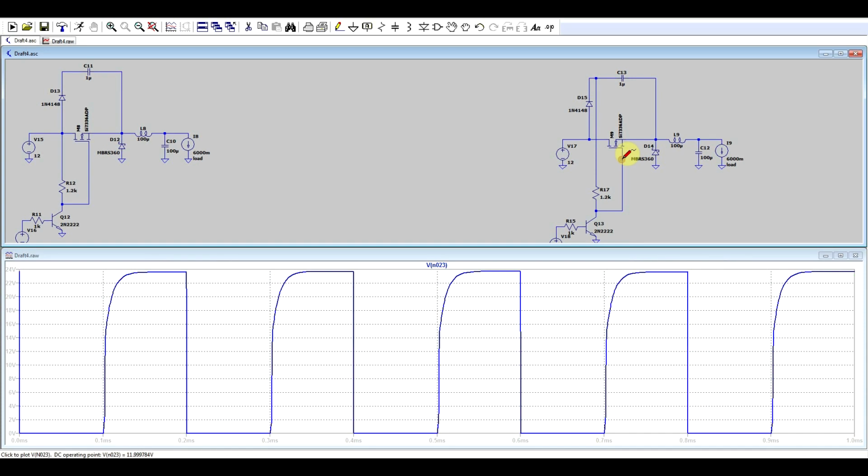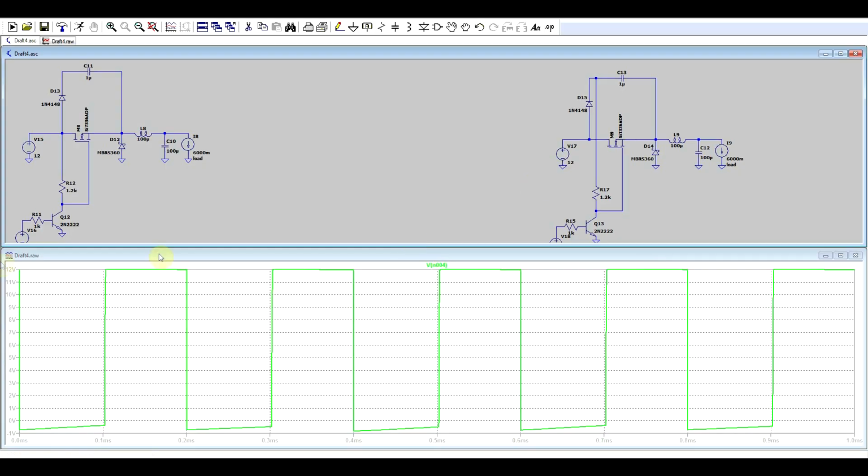And by doing this, the voltage in the gate will go from 0 to 20 something volts, so double that of the supply voltage in this case, and that means that the voltage in the switching node this time will end up at the supply voltage. So we no longer have that 1.3 volt voltage drop on the transistor. And this way we can get the supply to work efficiently. So this is the way to get the voltage drop on the transistor to be as low as possible,